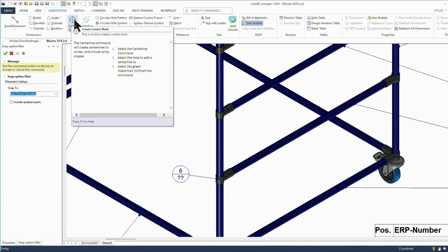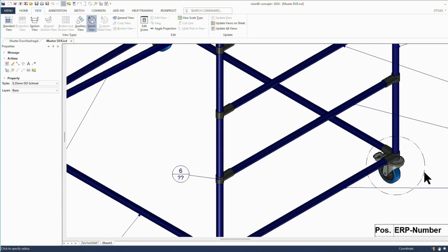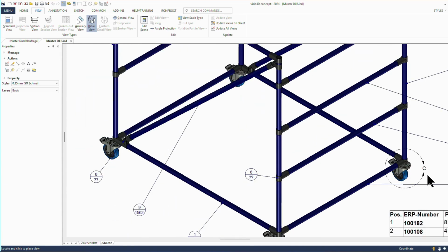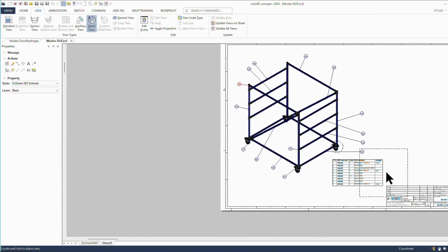This view, I can now optimize it by dragging the edges with the left mouse button. I'll drag my window upwards. This is now my detailed view. I can render it cleanly over the shaded representation over here. This is now view D. I can do this by selecting the properties of the window and telling it to please adopt my name.